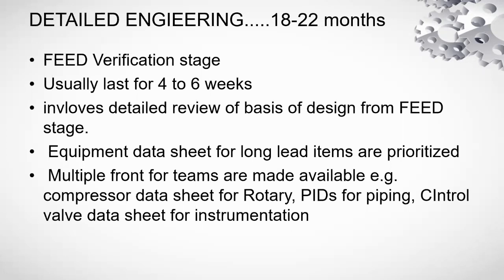An example I can give you is that we are expected to have a certain amount of nitrogen generated as a utility at the site, and the type of nitrogen generation, whether it is from membrane or by other ways, ideally should be finalized during the FEED stage. But utility, in most of the cases, is neglected.